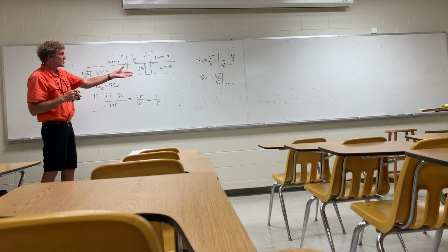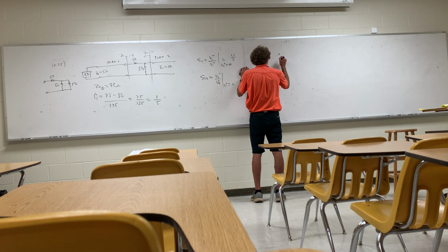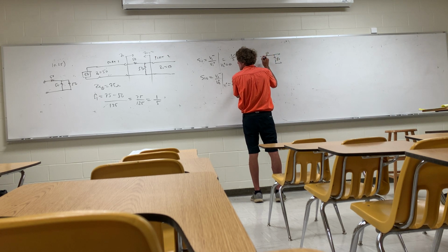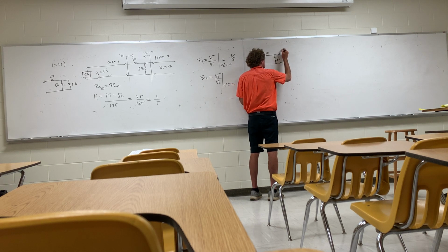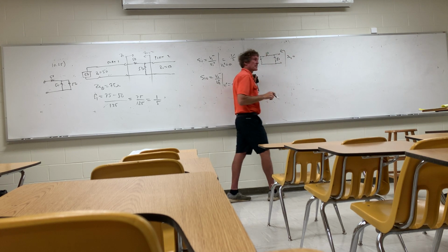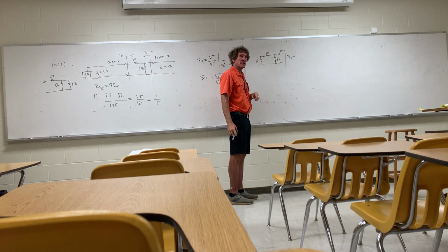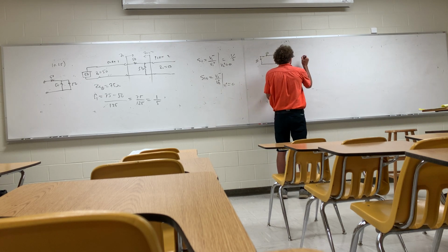All right, so again, what would Z in here be? Just draw it up. This is port 2, right? We're looking in here. First thing we have is a 50 ohm right here, right? That's 50 ohm. And then you got 50, and you got 50, don't you? This would be the transmission line. So what's the input impedance here? It's 33.33. I've got 50 in parallel with 100, or you're right, I think it's 33.33 ohms.